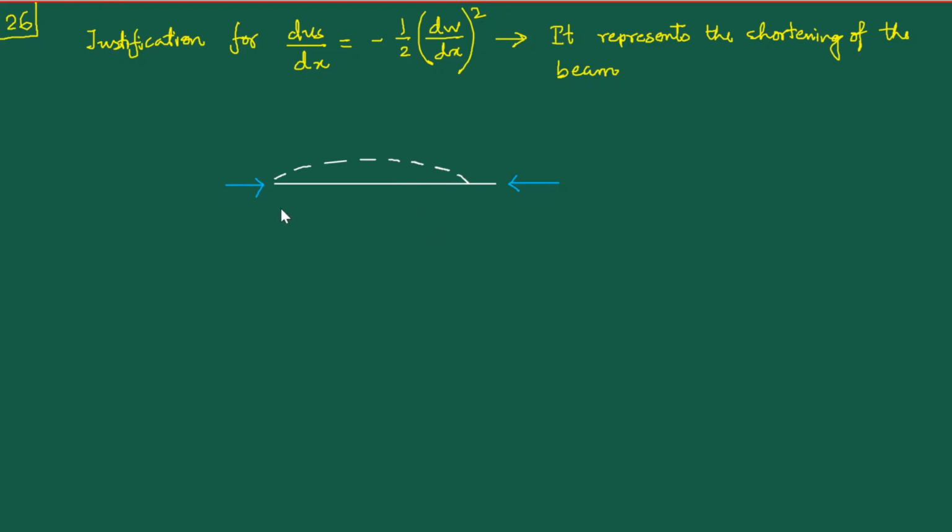So what is happening is that when the buckling really occurs, the shape of the beam becomes like this, at least in the first mode of buckling. Of course, when I say first mode of buckling, you have to understand that immediately associated with that statement is the specificity of the boundary conditions, but right now I'm not too much bothered about the boundary conditions. So you understand what is going on here: there is a beam, and as a result of the axial load, it is going to be bent out of shape like this. That is when we say that it has buckled.